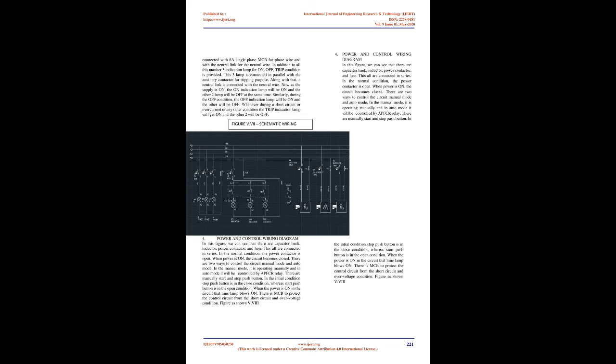This is for the protection of the indicating lamps. An air circuit breaker is used, which is mainly used to provide overcurrent and short circuit protection. In this ACB there are on, off and trip indication lamps, and an off/stop push button is provided. An APFC relay is provided and it shows balanced usage of capacitors based on the number of switching operations and connection time of each step.